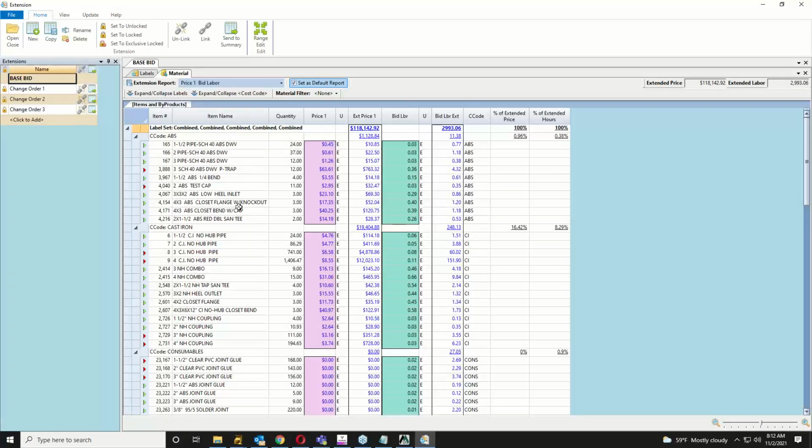So it's going to go through and tell you that, hey, your 4-inch cast iron in total on this project, we're looking about 1,400 feet. It's going to cost you $8.55. So getting it from a supplier is going to be about 12 grand. At 0.11 man hours per foot to do the install, so you're going to be slinging 4-inch cast for about 151 hours. So you have that detail for everything.